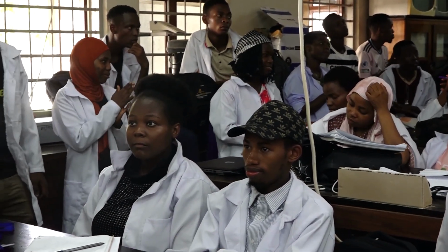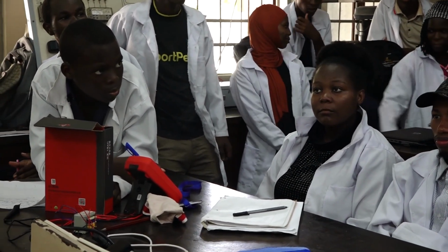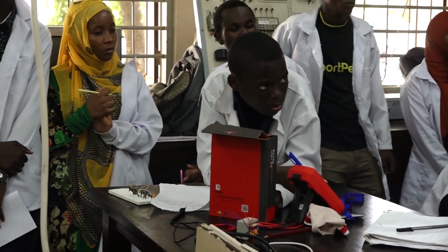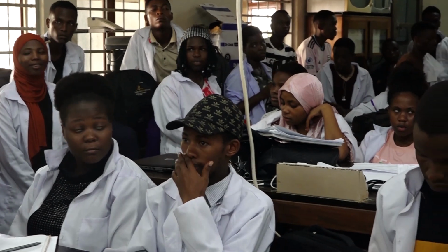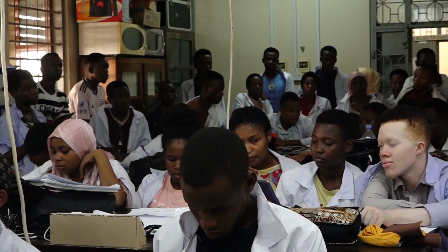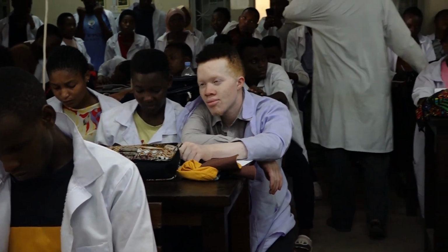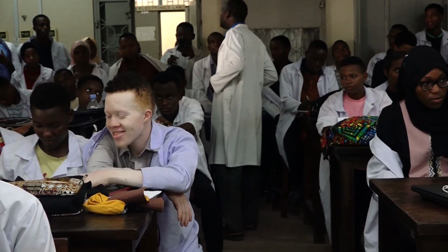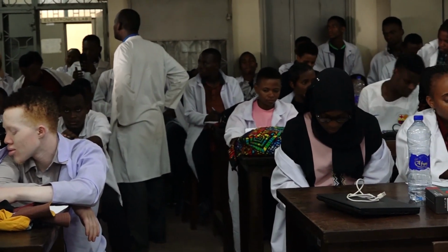But before we congratulate him, I know some students in this class still have an argument. Just take 60.677 multiplied by the square root of 2, because root mean square voltage is equal to the maximum voltage over the square root of 2. Or, to verify the reading from the digital oscilloscope, it's 10.82, that's the maximum. Divide by the square root of 2, then you get the root mean square voltage. Do it quickly, it's simple mathematics, no need for a scientific calculator. The square root of 2 is what? 1.414. Divide 10.8 by 1.414.